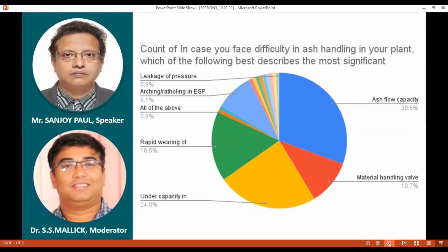Suppose you require X amount of air, and the existing compressor has a capacity of 0.8x. If you add two compressors in one line, opening the isolation valve, then the airflow will be double, but the requirement is x, and you are providing 0.8x into 2, that is 1.6x.